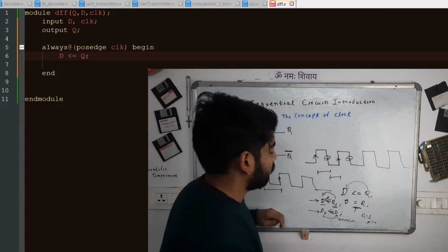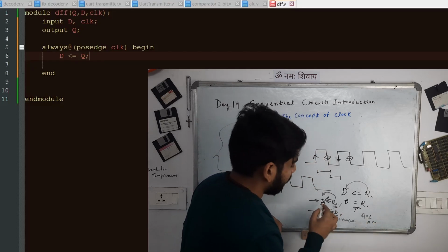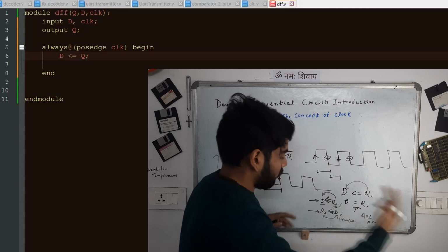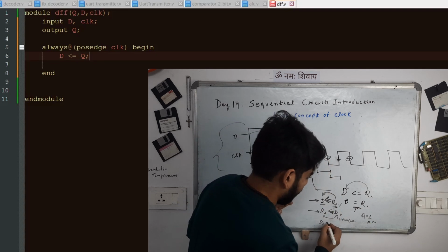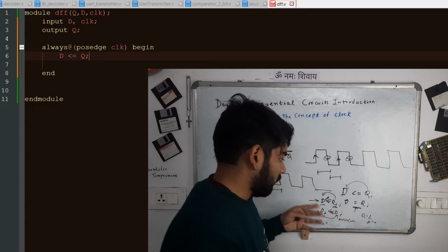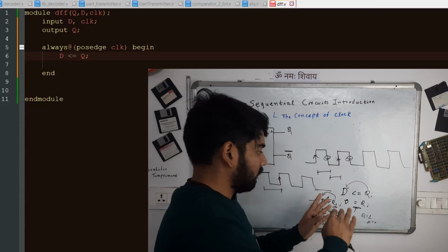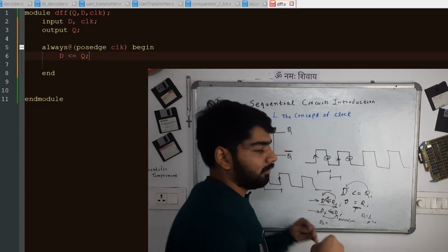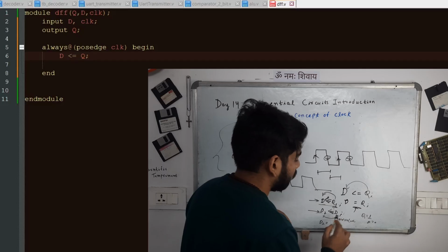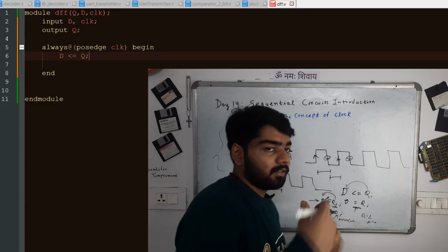So in this case, what is going to happen is basically Q1 is 1 and D is currently 0. In the next clock cycle, as soon as this triggers, what is going to happen? D2 is going to have the old value of D, because D hasn't changed yet. Okay, this will be calculated basically in the same edge, same clock, and these two are not calculated one by one. This will basically take the old value, and D2 in this case will be 0 and D in this case will be 1 after the clock edge.